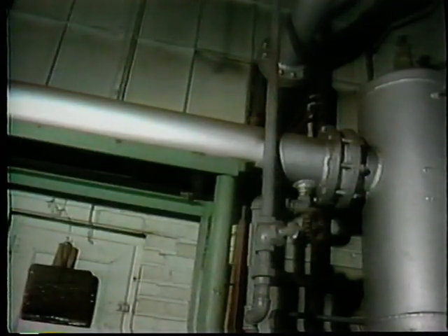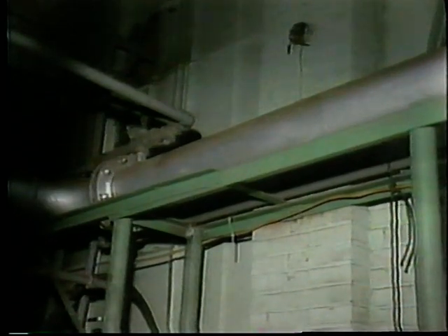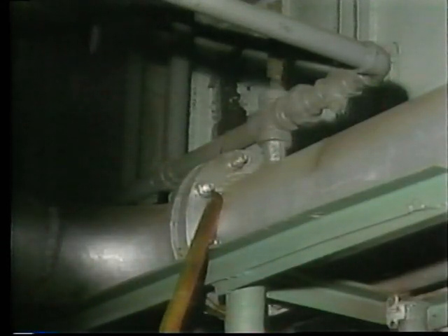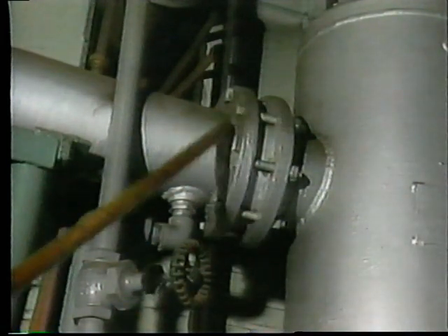That's why several techniques are used to reduce and in some cases eliminate contaminants. Let's begin right at the compressor output. First, instead of discharging the compressed air directly into an air receiver, it is passed through the device you see here. It's called an aftercooler. As the name implies, an aftercooler cools air as it comes from the compressor. This is the air inlet, and this is the outlet or discharge port.